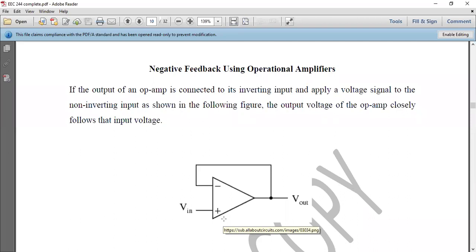The negative terminal there and the positive terminal, they take in signal to the amplifier. The amplifier now checks what is the difference between the two. If you are putting in 2 volts from here, and 3 volts from here, the amplifier checks what's the difference between the two. So it will be 3 minus 2, and that is 1. So it means the 1 is entering from positive here because here is higher. The positive voltage is higher than the negative voltage. So that 1 will enter through V in plus, the input terminal plus.